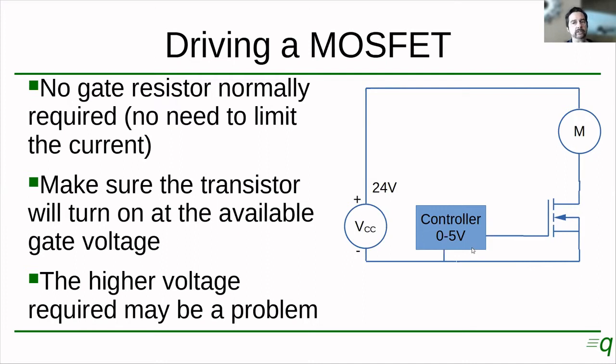Now, there are some special high switching applications, or sometimes some conditions in the circuit, that make it better to put a small resistor here, maybe about 10 ohms or so, okay? Just be aware of that, but normally this is not required.